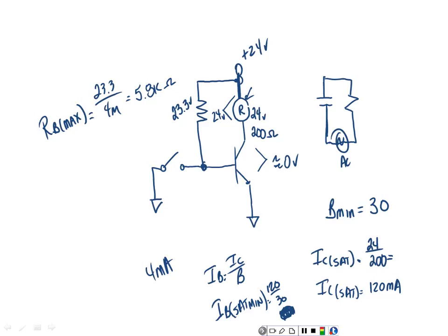So we'll show you how to get rid of that counter EMF. We'll try to demonstrate it to you while we're in lab. We'll get a coil and hook up DC to it. We'll charge it up with 12 volts, and then we'll discharge it. About 70 volts, yeah. We did that in AC. We've got to worry about that here, right? You understand that? It just takes a diode. It's not very much. See y'all Wednesday.